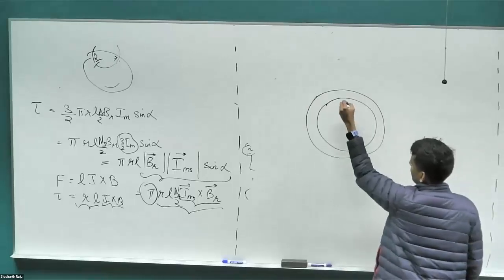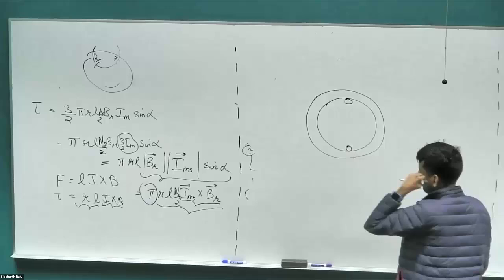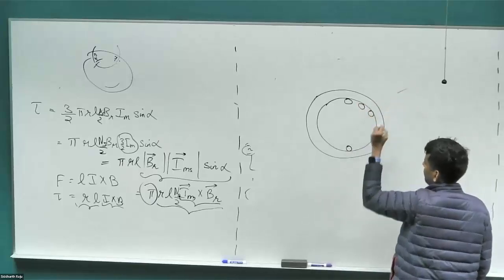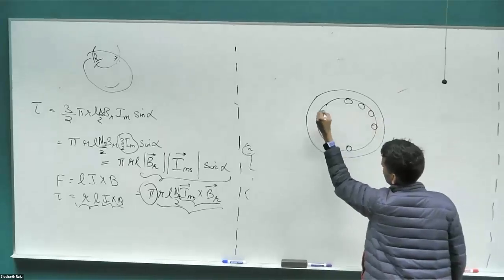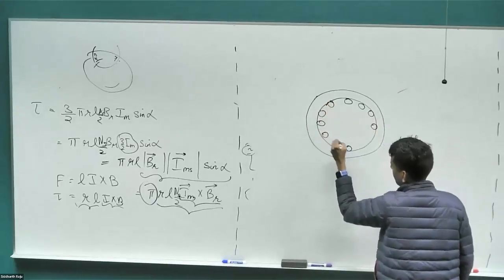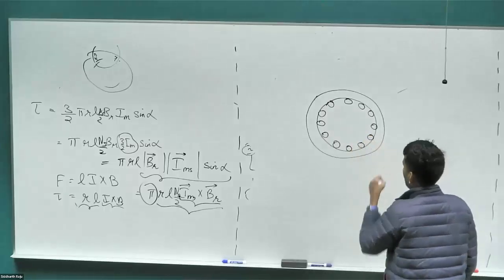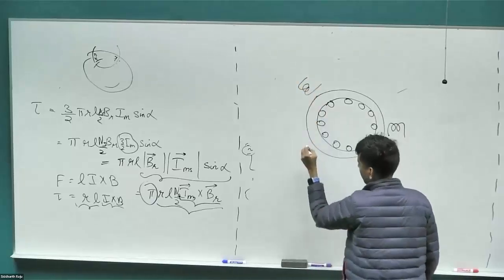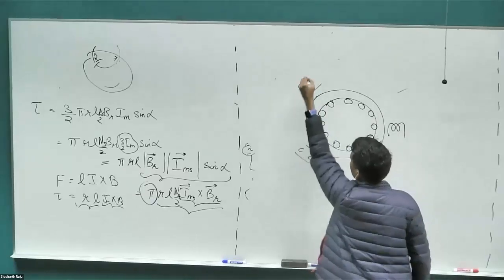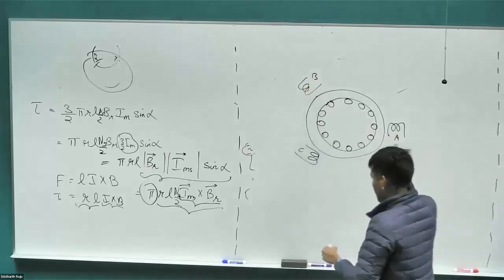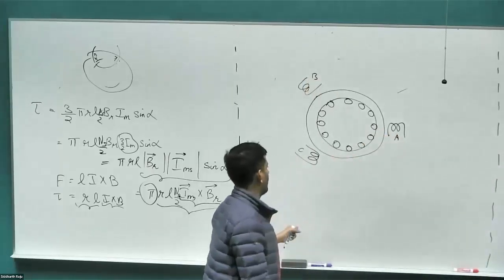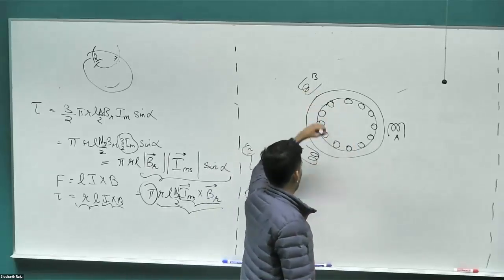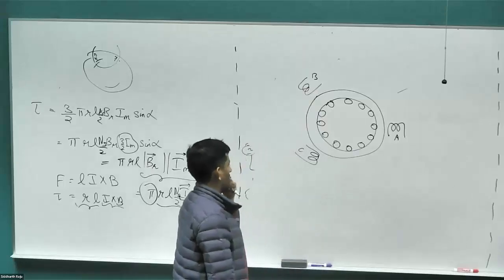We have a stator structure, we have a rotor, and there are a bunch of bars. So I'm looking at it from the top view. These bars go all the way behind the board. This is the rotor, and then the stator, we still have the sinusoidally distributed winding. That still remains the case for the stator. That hasn't changed from a permanent magnet synchronous motor versus an induction motor. Right, so each of these bars are basically shorted on the top and shorted on the back as well, with some finite resistance for each of the bars within them.